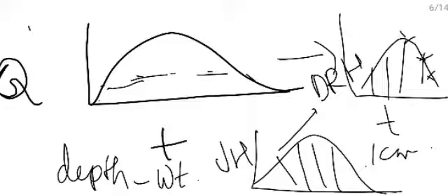Now, to match with the duration, what do you have to do? If the unit hydrograph available with the meteorological department is a 4-hour unit hydrograph, then after 4 hours you draw the same unit hydrograph again. So suppose the duration we want is 8 hours, the same can be drawn.